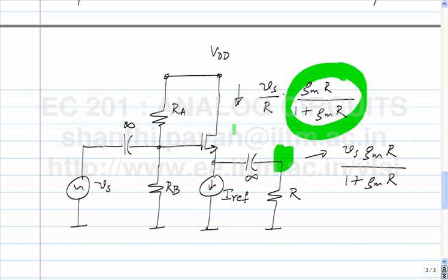Now, where have we seen this? This is a characteristic of negative feedback systems. Do you all understand that there is negative feedback here? That's how in fact we derived it. We take I times R, we compare it with V in and go and tweak the current until I out times R becomes equal to V in.